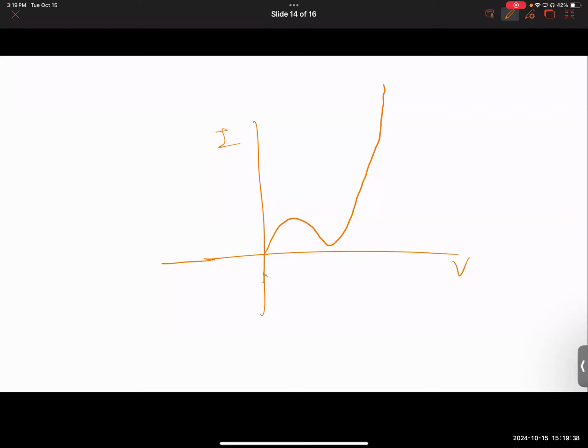As an engineer, you should start looking at opportunities in something weird. Like there's a lot of opportunities in weird devices. This was the very first observation of a negative differential resistance, negative resistance. Here is how. I just told you, IV. If you take an IV curve here and take di over dv, which is the slope of the curve, and take an inverse of it, what do you get?